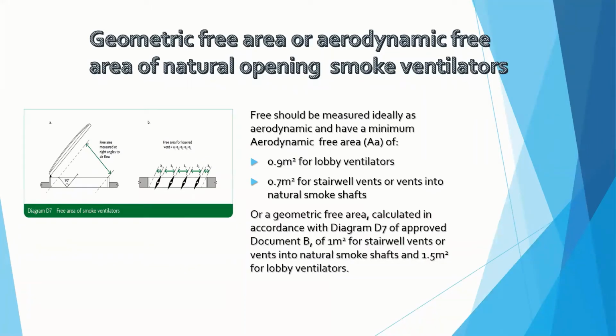It is not acceptable to estimate or guess the free area or aerodynamic areas of natural opening smoke ventilators, as this could have a major impact on the smoke control design. It is important that sizing is based on the free area that has been measured accurately, following the relevant guidance or measured under test.